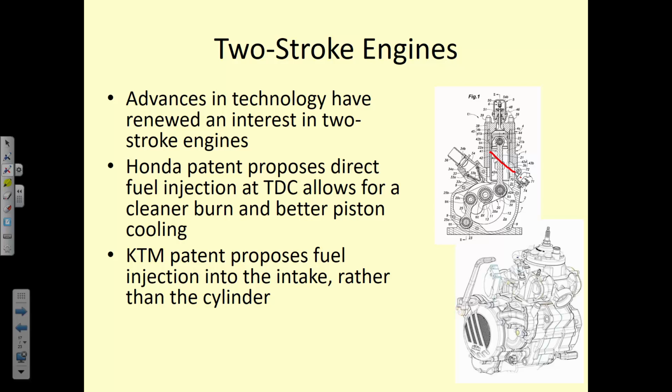They spray the fuel as the piston is almost at top dead center, so the self-ignition will occur at that point. If they're able to spray that fuel in and have it combust completely, then the emission byproducts are a lot cleaner, both because it's a more complete combustion and because there's not additional fuel coming in as you exhaust. So they're able to get very high power to weight ratios, but still also pass emission standards.